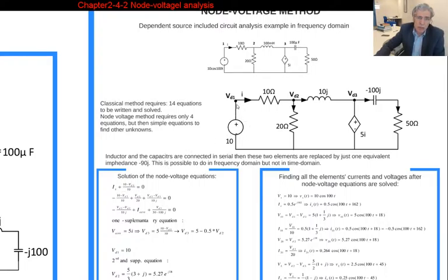Here there are two elements connected to node 1, and both of their signs are plus, because the current reference for this independent voltage source is downwards according to passive sign convention. Both of them are coming out of the node, therefore both signs are plus.